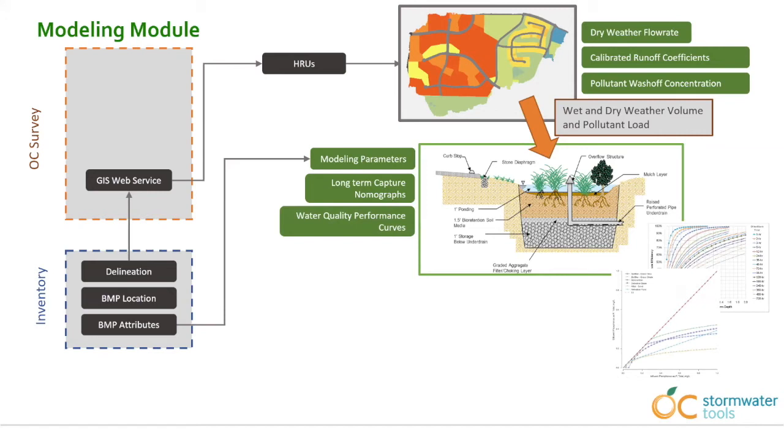And the advantage this gives us is that we can have a robust relationship between a BMP's influent concentration of a particular pollutant of concern and the effluent that we would expect to see from that BMP. And so with these fast lookup tables and functional relationships, we can transform our influent volume into our treated effluent volume for each node, and then move to the next downstream location and repeat the process.